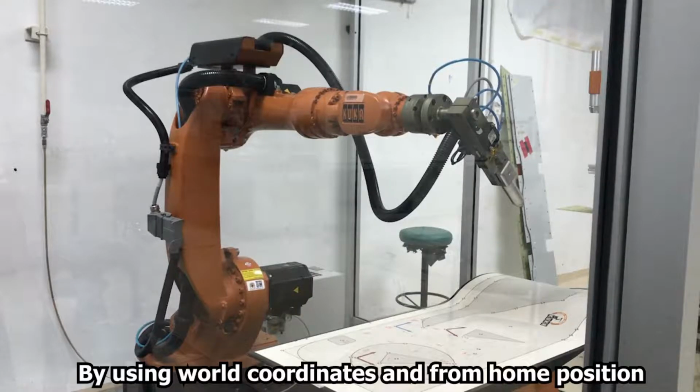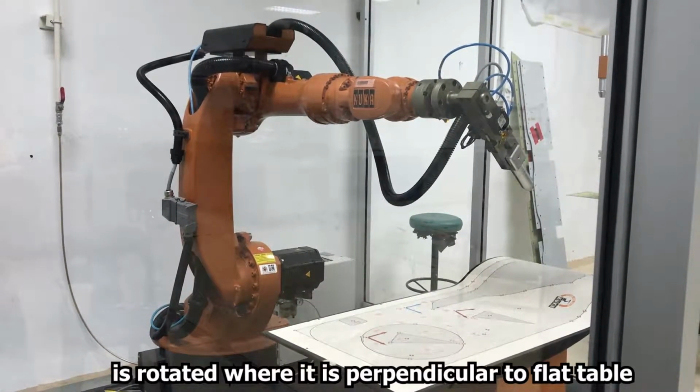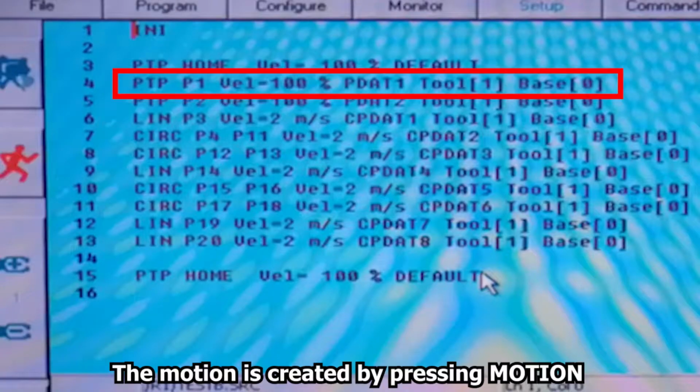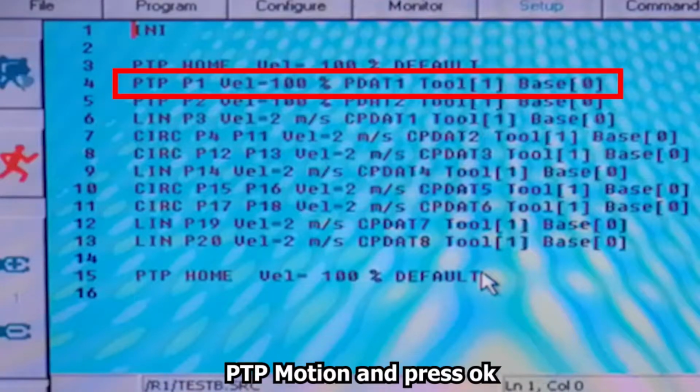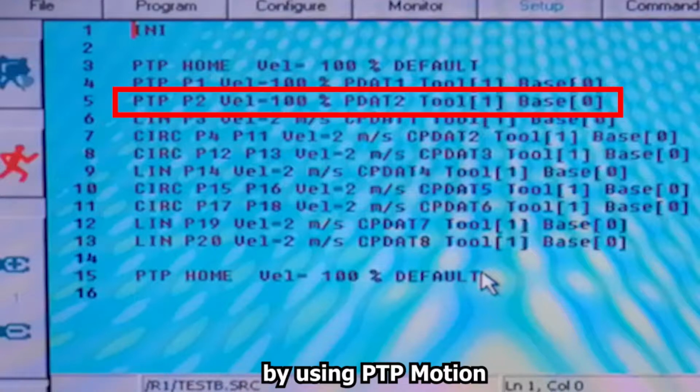By using world coordinate system and from home position, the pen mounted on the KUKA robot is rotated to a position where it is perpendicular to the flat work table. The motion is created by pressing motion, PTP motion and press OK. Then, the pen is moved towards the first point of the contour on the work table, by using PTP motion.